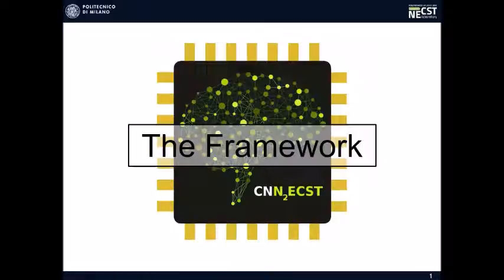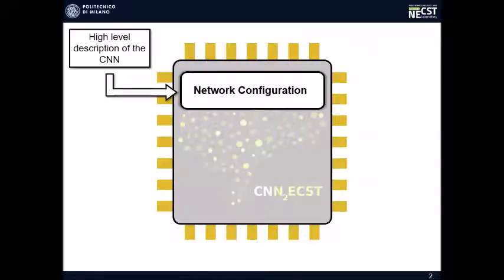The application has a simple interface that can easily guide the user during the design process. As input, the framework only needs a file with the weights of the network that can be trained offline or randomly generated to test the feasibility and the performance of the hardware implementation. Then the workflow goes through different phases: the network configuration, the resources estimation and optimization, and the hardware generation.